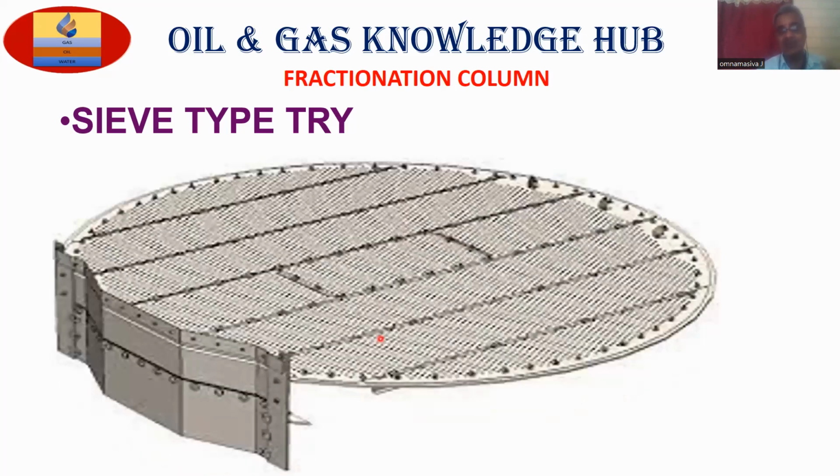So, this is called a sieve tray. This is a weir plate. Liquid will come from bottom to upwards, it will travel. From this weir, heavy liquid will come to the downcomer. This is the downcomer. From the downcomer, it will go to the nozzle, as I discussed in the previous slide.